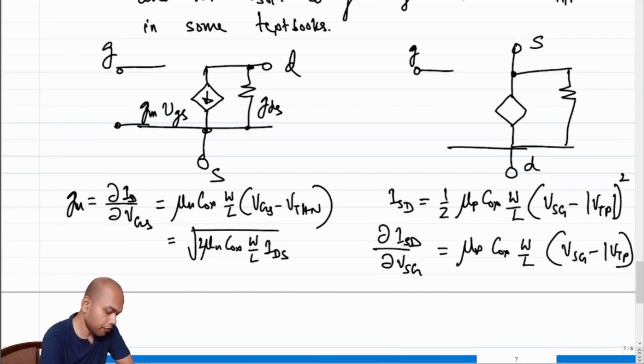So let's say this is the source terminal, this is the drain terminal, right? So if we call this GM, and we keep the same current direction as in the MOSFET, because again we don't want to learn something new unnecessarily if we can draw a parallel between some things we already know. So we don't want to change the incremental model, right? We are trying to see how far we can get without changing the incremental model and learning a brand new thing, right?